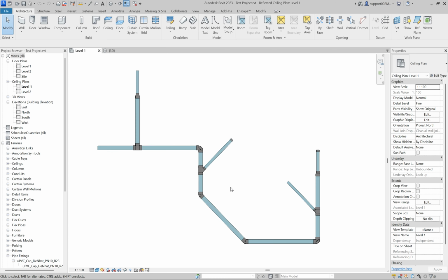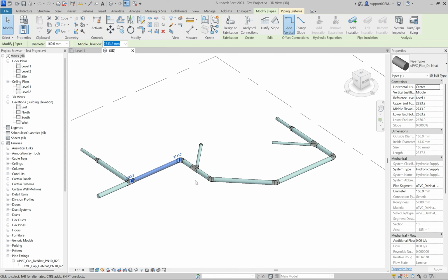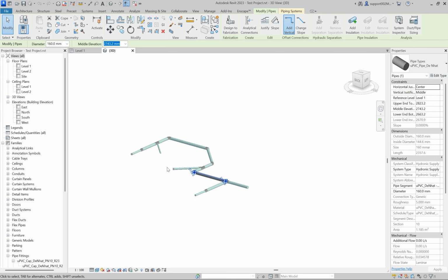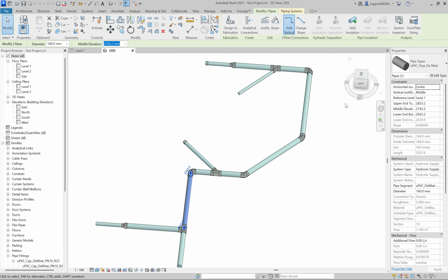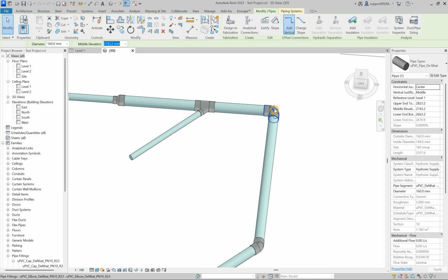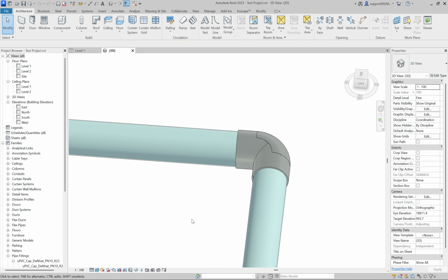Hello everyone. In this chapter, we'll learn how to create pipe fittings using lookup tables with the size lookup function. Lookup tables contain type data, allowing you to define multiple part sizes without having to create separate family types for each one. I'll walk you through the process step by step, first creating an elbow, and then using it in an actual project with the appropriate pipes.